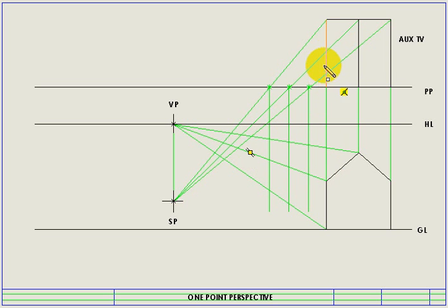It is also connected to this point over here in my top view, and if I follow it, it would go to this point on the picture plane, and then project it down as an upper point and a lower point.